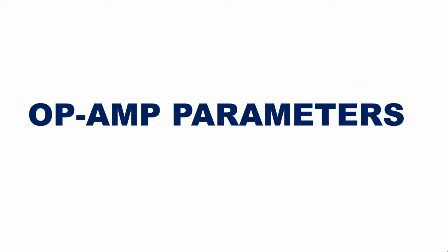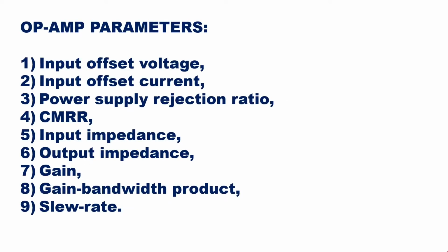So the topic will be OPAMP parameters, and in that we are going to see what is input offset voltage, input offset current, power supply rejection ratio, that is PSRR, then CMRR, common mode rejection ratio, input impedance, output impedance, gain, gain bandwidth product, and slew rate. So these are important OPAMP parameters.